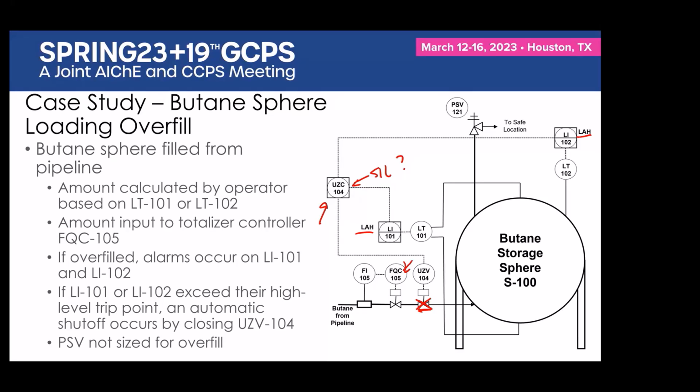and most of the time when you're in a LOPA, the failure of the operator to respond to alarm is a very specific taxonomy. An operator is sitting at the control station, an alarm comes in. The operator needs to verify that the alarm is valid. They need to determine what caused the alarm to occur.